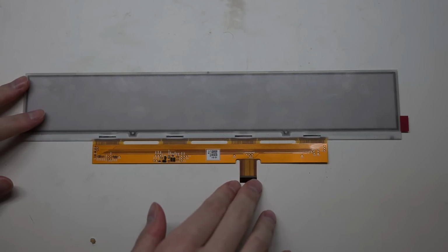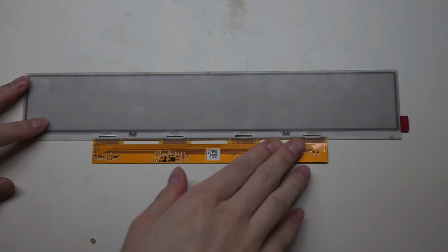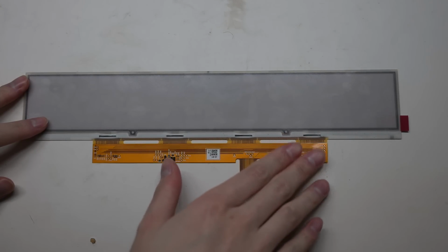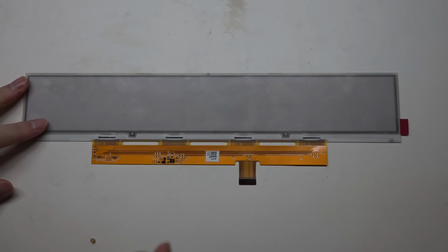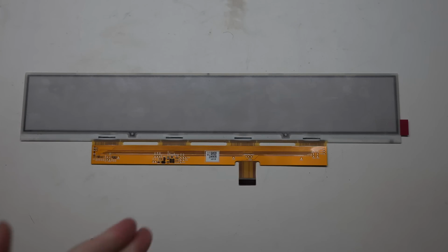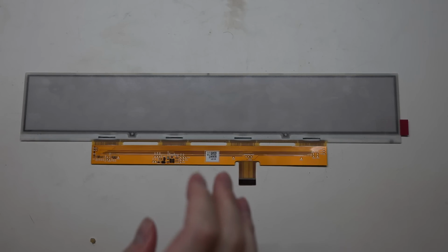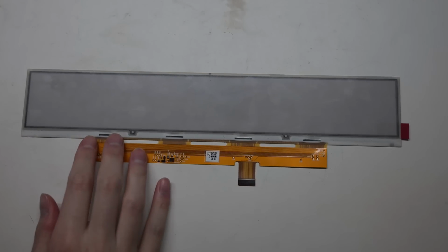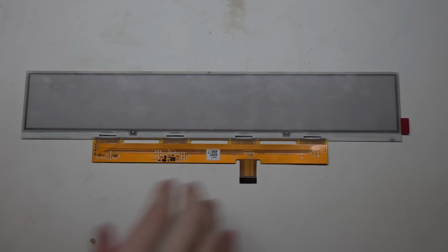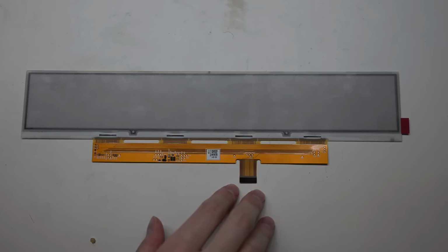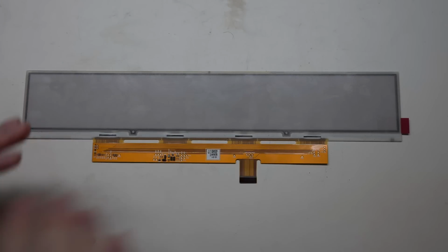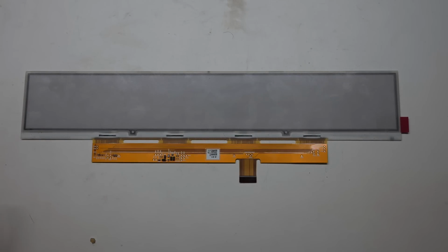I should say this method is still possible here, but I need to reverse engineer this FPC first before I can make some observations about what each pin might be, then start guessing. So this is still a possibility I can take if I couldn't identify the chip, right? Another possibility, which unfortunately doesn't apply here, is to find other screens that share the same pinout. This is a very, very effective method, especially with E-inks, because E-ink is one single company. It makes sense for them to produce different screens with the same pinout.